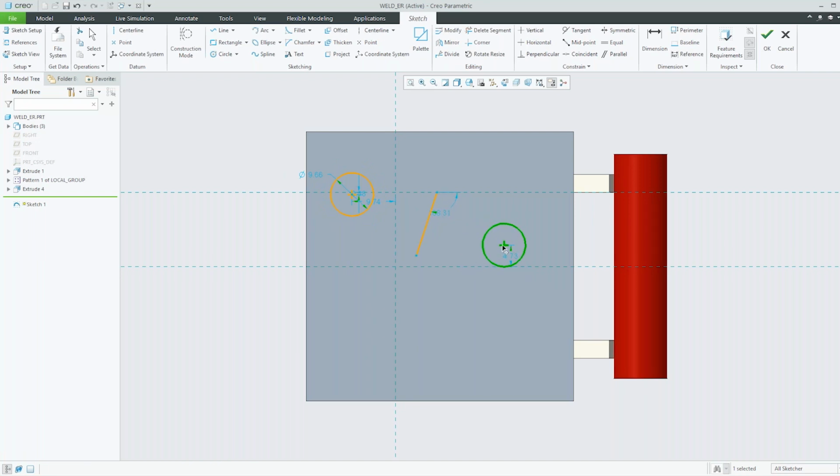Notice as I'm dragging it though, this is a different behavior we haven't seen before. We saw before, I think it was in Creo 5, where we can do a mid-plane. We can pick two planes and say, make a datum plane midway between them. That's kind of what this is doing. As I move them closer together, it keeps them, and I can also move it this way. It's extending out. It's actually moving the center line to stay in between the two as I drag them, which is a different kind of behavior than what we're used to seeing.